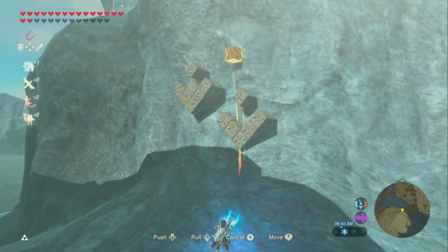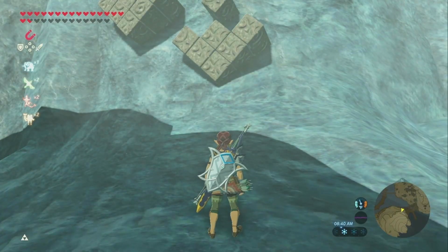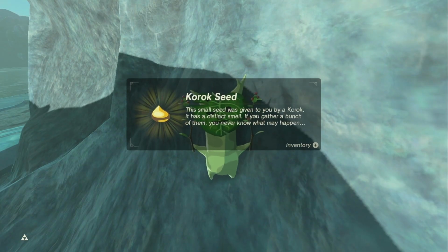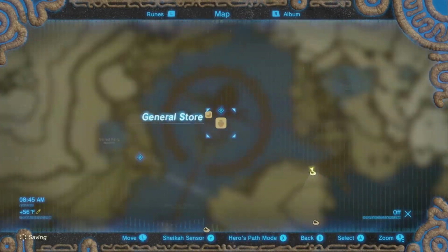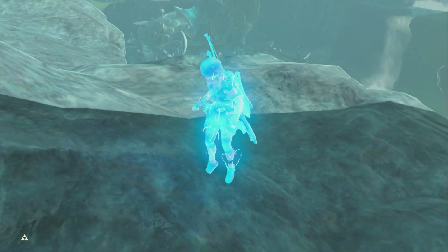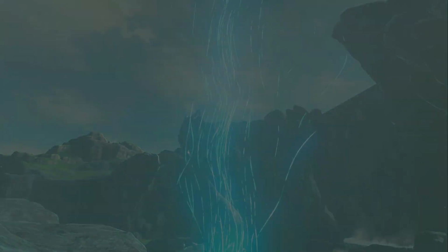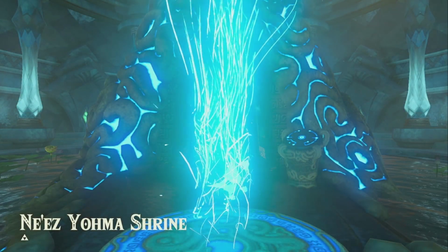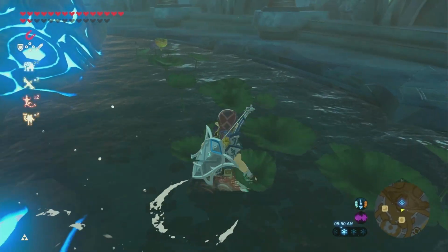And then it says here, other improper locations. Less than 12 inches below soffits, below 18 inches from an inside corner, below 24 inches from an outside corner, below 3 feet, or 6 feet in Canada, above mechanical air inlet if within 10 feet horizontally, less than 12 inches below deck, balcony, or porch, bracket must be open on 2 sides.